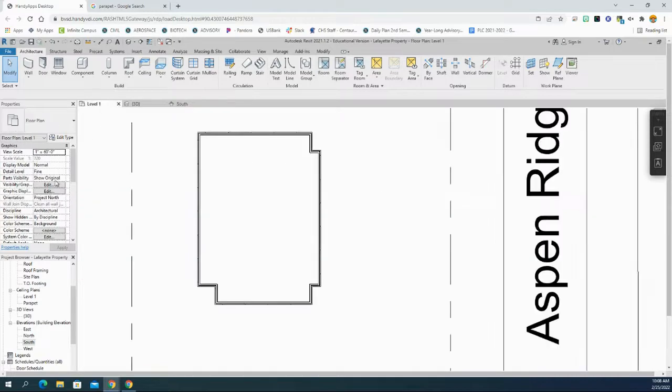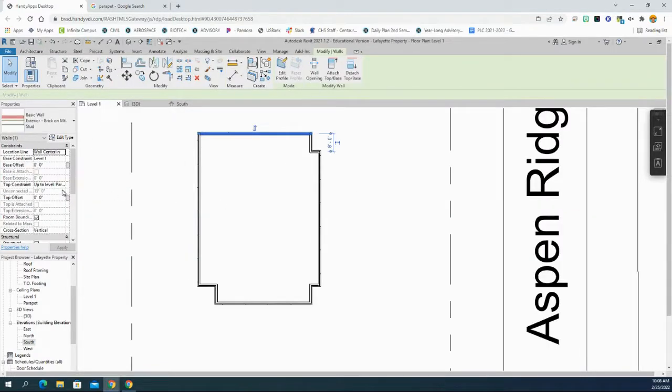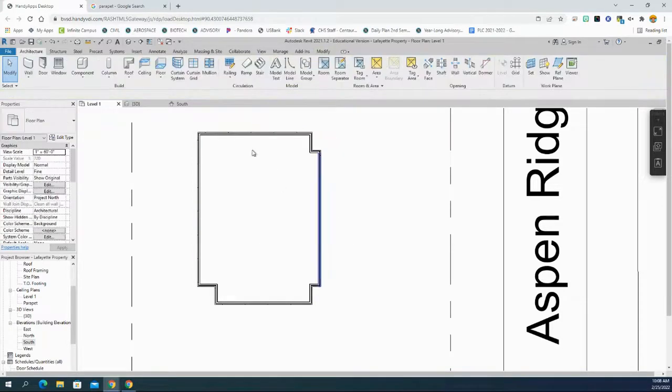It's also why I'm not choosing an unconnected wall. That, again, is an option. You can make it unconnected and set it to whatever height you want. But then if you ever make any adjustments on your elevations, then you're going to have to manually adjust these. That's why it's really nice to have it set to a constraint. So this will be all that we're going to do for the basic design of your walls. Go ahead and draw in your design, and you'll have your basic outline set. I'll show you how to add windows and things in later videos.